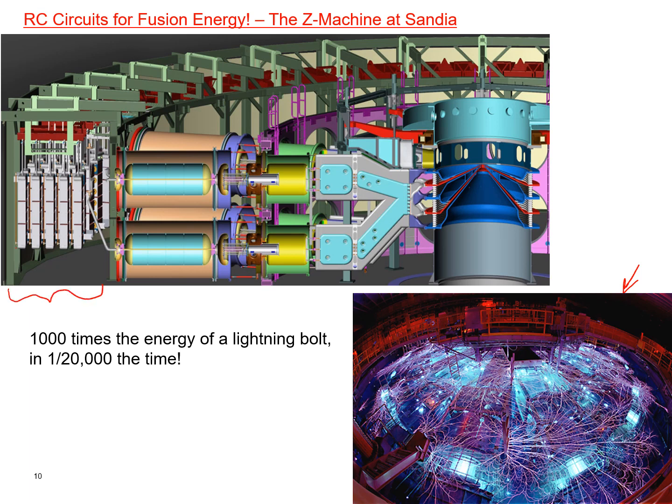Then all of their energy is quickly transferred to another set of capacitor banks out here. And then even more rapidly, they transfer all that charge to the third set of capacitor banks out here. So you're going from a slower capacitor, which charges and discharges slower, to a relatively fast capacitor in the middle, and to an extremely fast capacitor at the end.